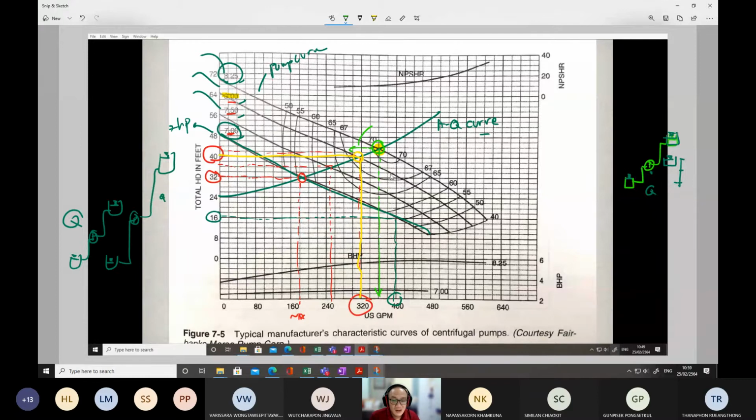The curving lines like this show the efficiencies of the pump. So the pump has various efficiency depending on the conditions it works in. If you choose, for example, the 7, which is the smallest one, under these working conditions the efficiency will be only 55%.